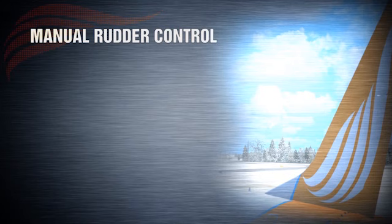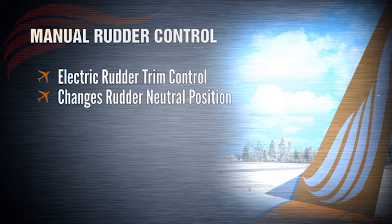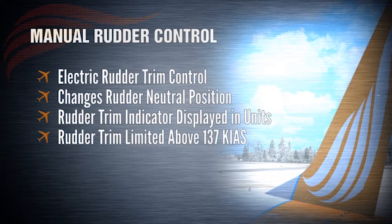The rudder may also be operated manually through the electric rudder trim control. This changes the rudder neutral position. One of the two rudder trim switches inside the single rudder trim control is connected to the Flight Data Acquisition Unit, FDAU, to record rudder trim position. The rudder trim indicator shows the amount of rudder trim in units. Rudder authority is limited when airspeed is higher than 137 indicated knots, in order to provide protection after takeoff and before landing.